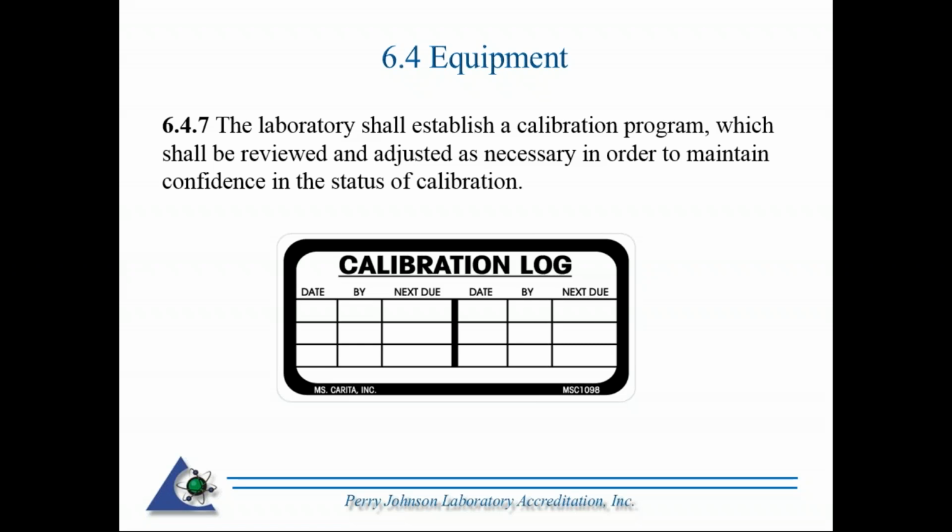Often questioned is the calibration interval. How long should that be? Well, it's something the laboratory needs to look at. Let's say, for example, you put an item out for a year, and you have 5 years of sending the instrument out. Let's say it's a stable artifact, a mass standard, gauge blocks. And within that 5 years, you're not noticing any drift in the standard at all. That may be an indication that the calibration interval perhaps could be increased.